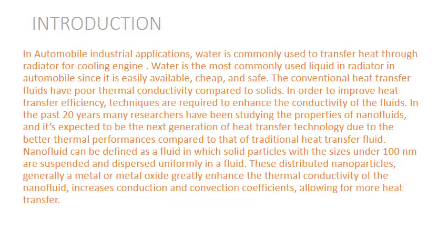But it does not have very good thermal conductivity, so we have used nanofluid, so that the heat transfer rate can be increased, along with the thermal conductivity and viscosity. We have not used microparticles since they would lead to abrasion and sedimentation inside the radiator.